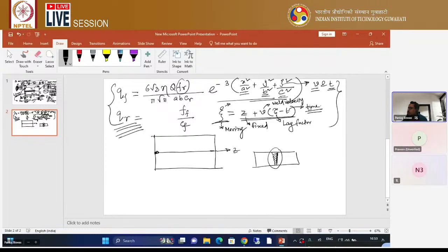Generally you need to define these from experimental observation, experimental fitting. Once you do the welding and complete the welding process, at the end there generally creates some crater. Crater means some depression of the weld bead due to weld solidification and its shrinkage. At the end, once you do the welding, you can observe some crater type of shape. Can you recall these things as well? Yes, sir.